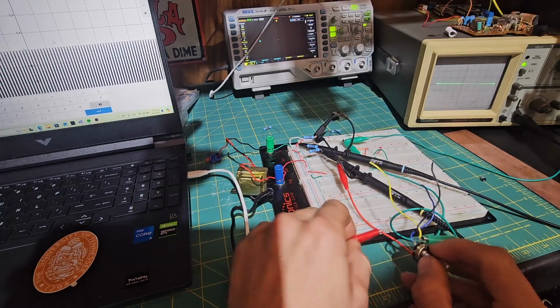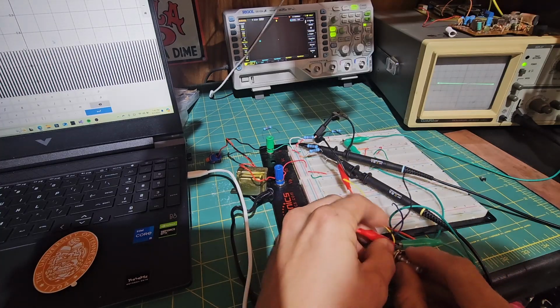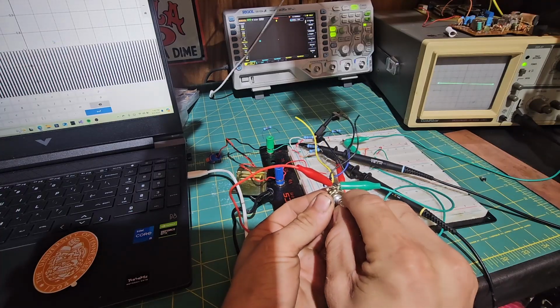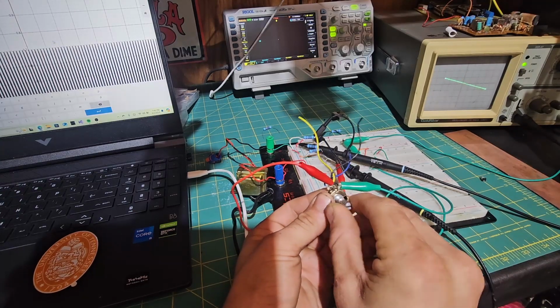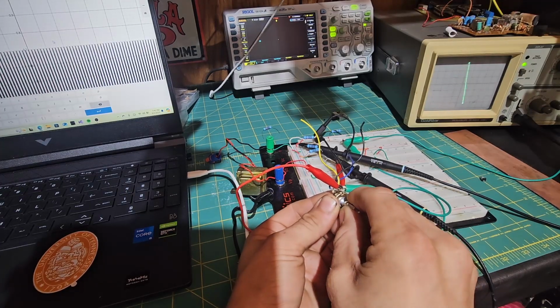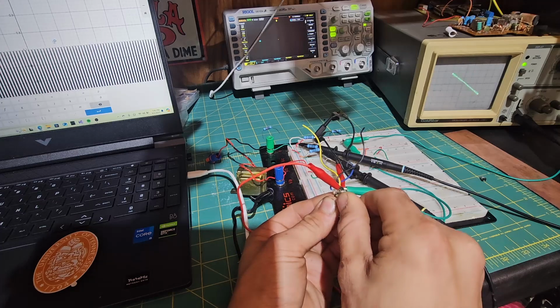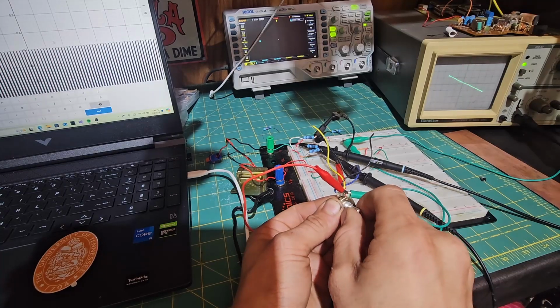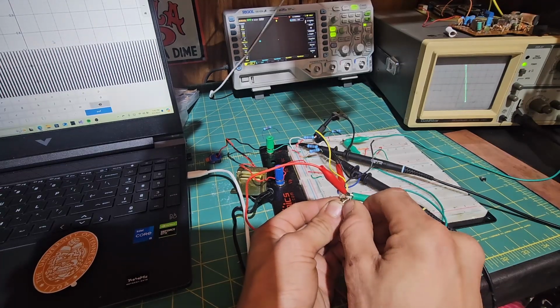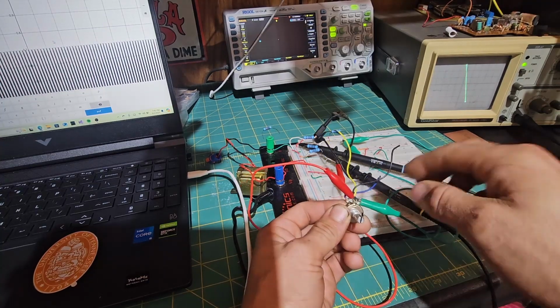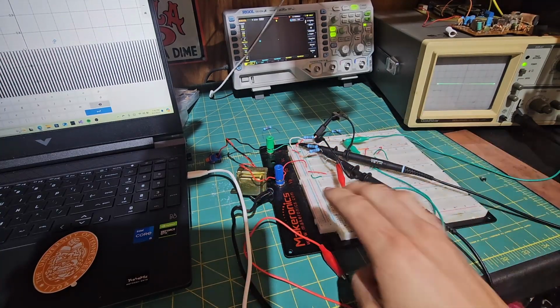Now this can clue you into a lot of bad audio components and things like that. So you can see here we've got this potentiometer, and when we turn it, we get a rotating line. That potentiometer looks like it's actually pretty smooth. There's not a lot of noise being presented, so that looks really good. I have an older one that I pulled out of an old radio because it was crackling and popping. You can watch it on this and it looks horrible. There's just noise everywhere with it. So that is what a potentiometer looks like.